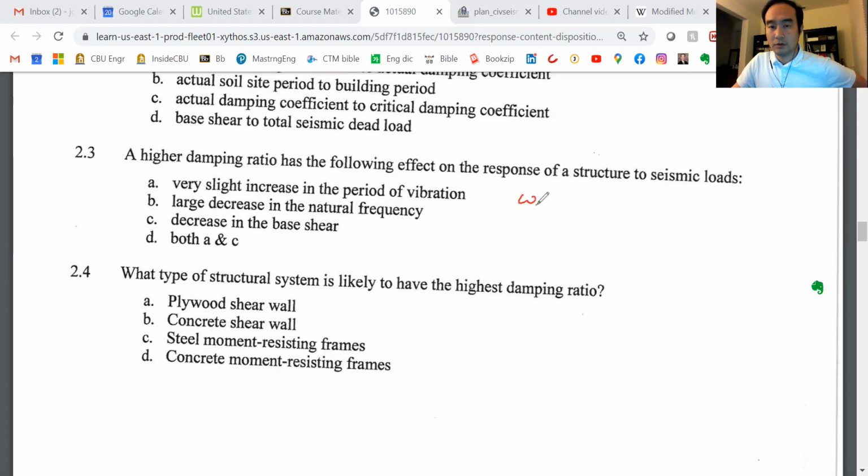So let's think about omega n, square root of K over M, and omega D, that's the damped frequency. We can calculate it as omega n times square root of 1 minus psi squared. So here we can find Tn. Here we can find Td.